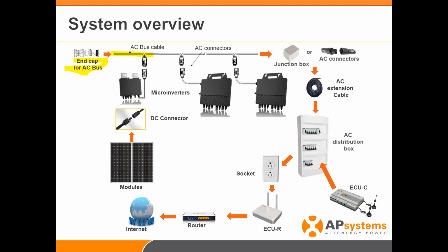You're going to come into the first drop, where you're going to collect your microinverters all the way down your bus line to a junction box somewhere on that roof. Every connector will be utilized in this particular case. In this particular case, we're showing 10 modules, YC600, 2 QS1s. Junction box, either you're going to make up your own connectors to go to a different junction box, or you're going to go through AC cable down to a distribution box here.